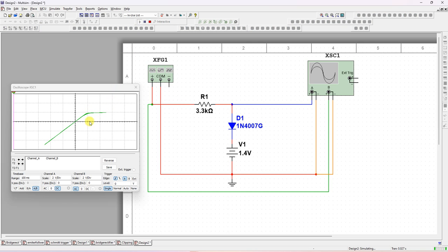See here. On the right side also, one box is 2. Channel A, x-axis. It is input versus output. So for one box, up to 2 volts, output is following input. So a diagonal line will come. After that, input is increasing to 3 volts, 4 volts, 5 volts, but output is not increasing. Output remains 2 volts only. That's why this portion is horizontal. Below 2 volts it is following. So this is the transfer characteristics.